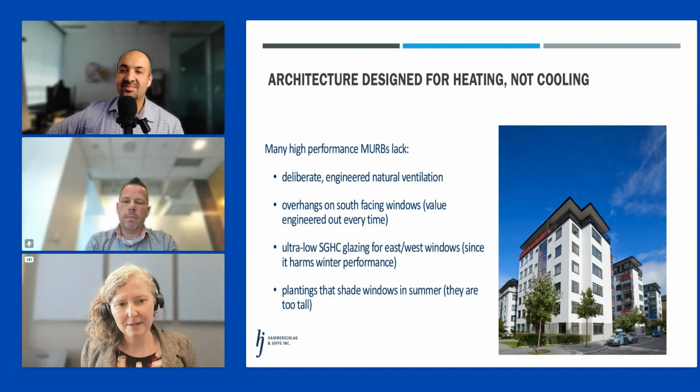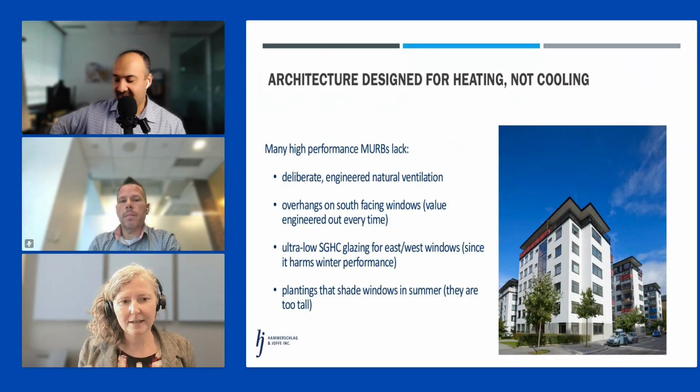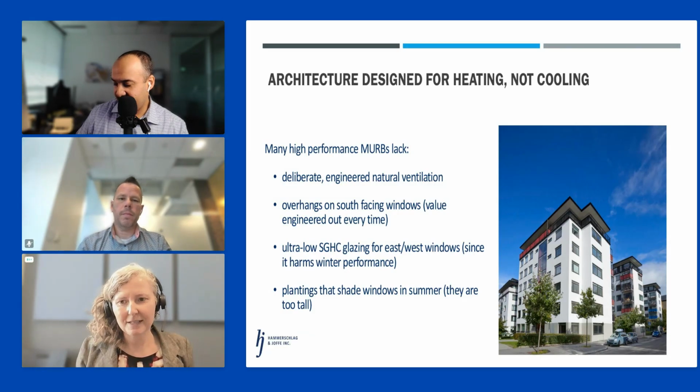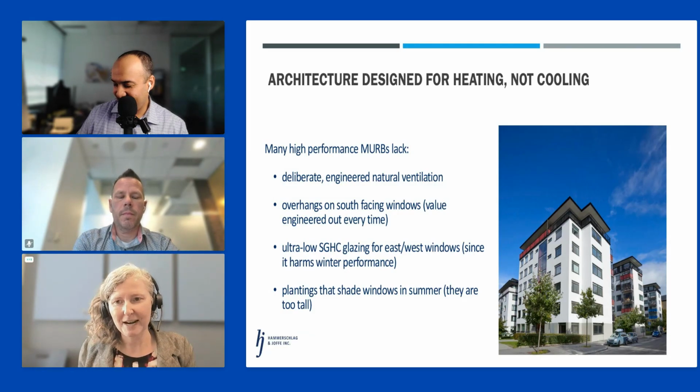So I have started advocating strongly for ultra low solar heat gain coefficients. I am talking 0.23, 0.18, certainly no higher than 0.32. And think about other ways that you can protect your building from overheating. This is a place where we have, in the upcoming climate emergency, life safety issues. We're going to have 9 months of cooling in Toronto by 2040. So designing a building for a heating climate when we are actually becoming a cooling climate is a real risk.